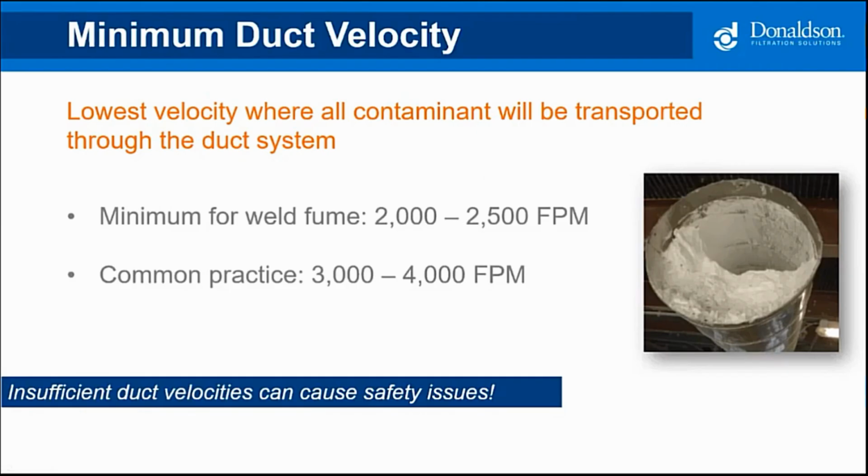The only thing in between the clean and dirty air is our fabric filter barrier and the level of dust on it. As the level of dust increases, so does the differential pressure. As the differential increases, my air volume drops. So if I start at 2,000 feet per minute and I've got around a ½ inch to 1 inch differential pressure on the collector, as soon as I start to work and I go to 2, 3, 4 inches before doing a reverse pulse clean, my air volume will drop, and now I'm below 2,000 feet per minute, and that's what we want to prevent.